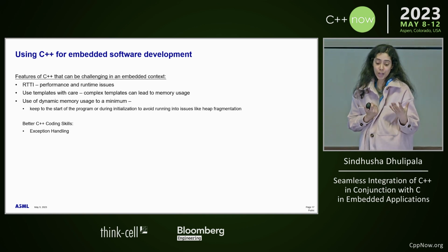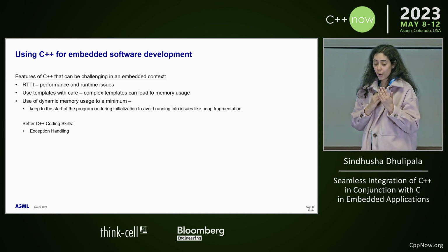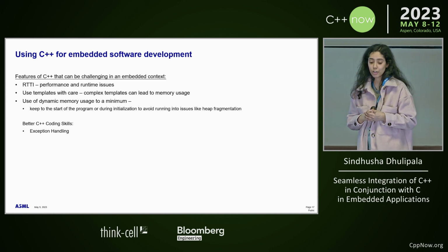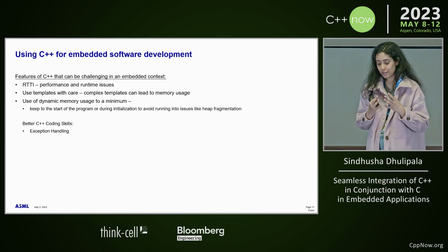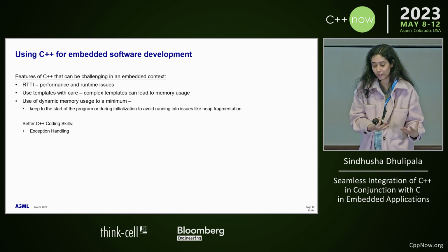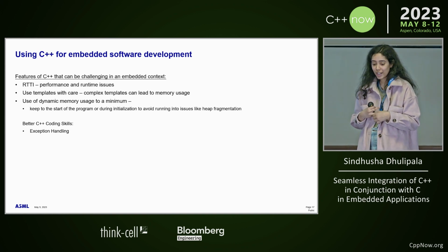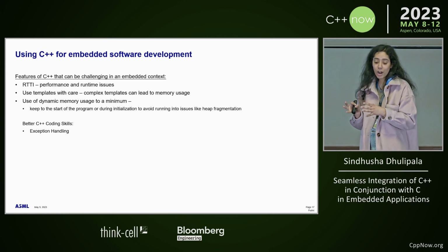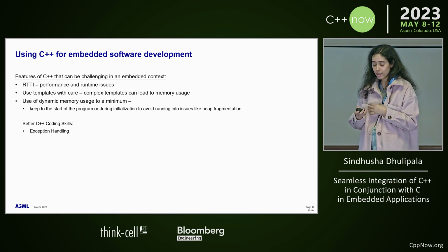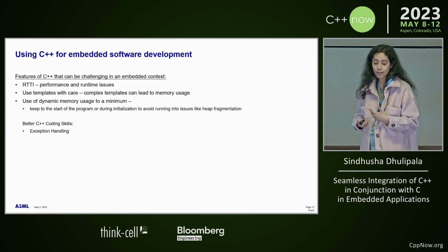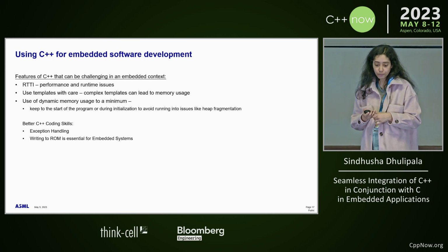Keep in mind, exception handling is amazing, but you always have to, just like at the application level, but maybe a little bit more for embedded, because there's a real world effect to it. You want to make sure that the error path you take is deterministic, and you know where it's headed and how you can test it, because in order to qualify your embedded software, you do need to be able to show that you've tested all paths of your code.